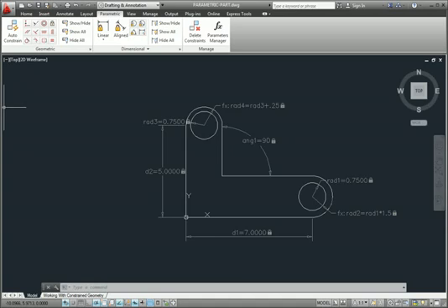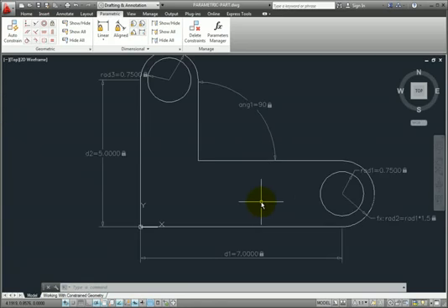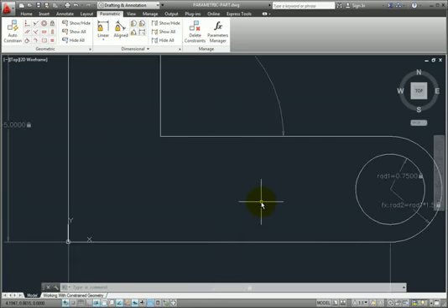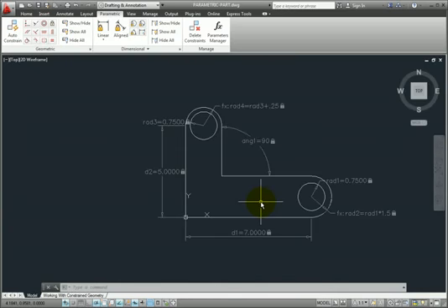By default, dimensional constraints are not objects. They display with a single style, maintain their size even when you zoom, and are typically not plotted. If you do need to plot dimensional constraints, you can change the format of a dimensional constraint from dynamic to annotational.